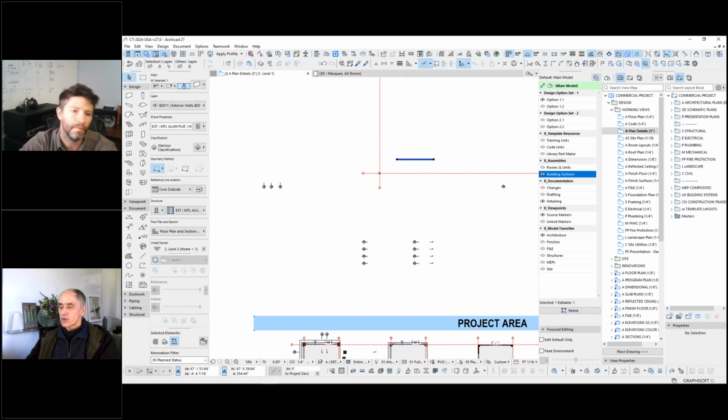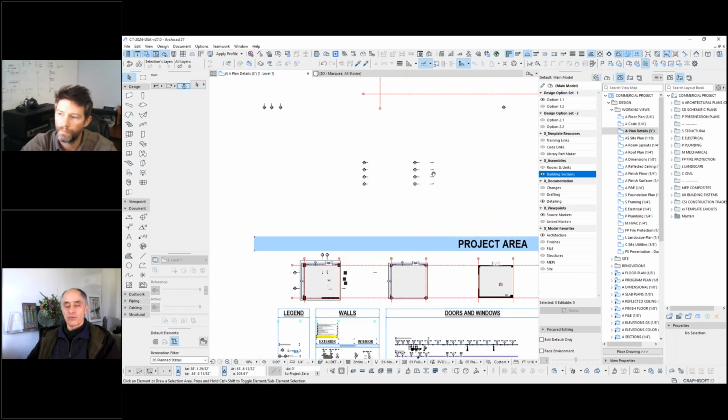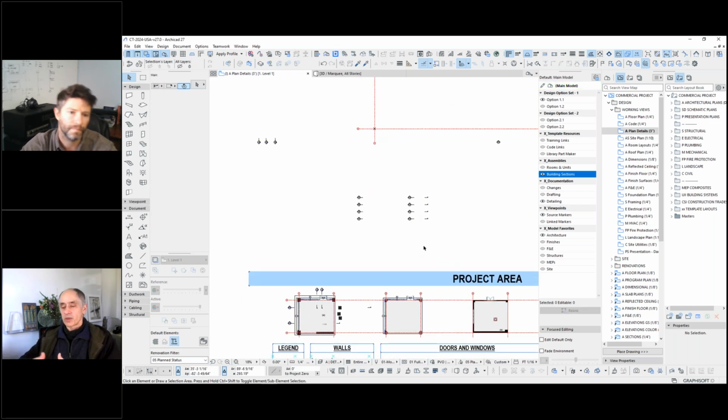Now, Rick Pratt says commercial buildings sometimes have a knockout for a future window. That's an interesting way to do it. You could have one option that has it filled and one option with a window in where the knockout is. What I found is, imagine that you have a slab and there's a different configuration for the footprint, or it gets bigger, you extend it out. Well, you can have two slabs next to each other. One of them exists in one option and it doesn't exist in the other. So then there's a smaller slab.